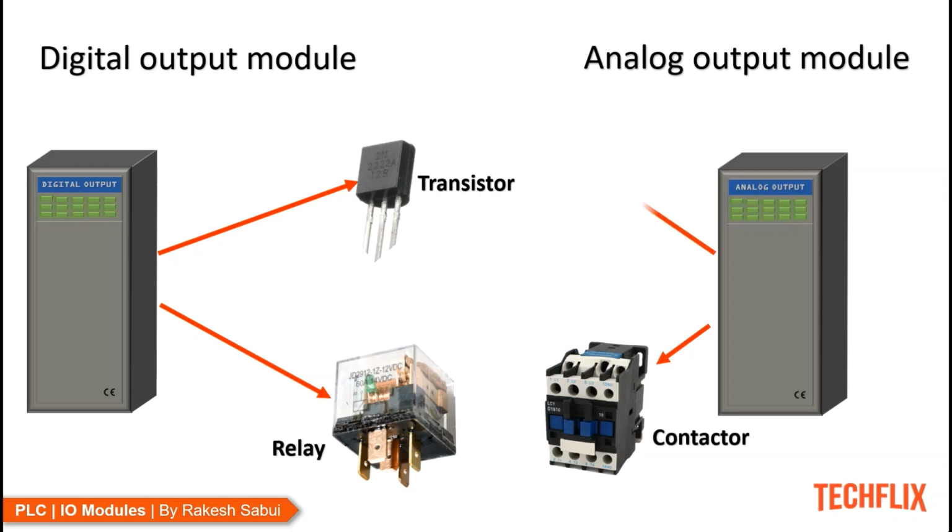The analog output signal can also be given through a triac. The triac is similar to a transistor. But the triac can handle voltage in the range of 230 volts AC. It uses the control signal at its gate to allow the higher voltage to run through it and power the output devices. A solid-state relay can be an alternative for a triac.